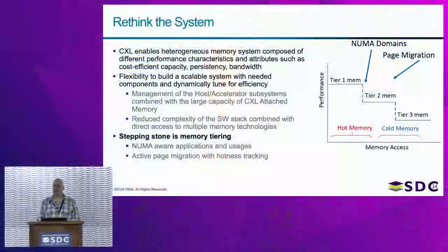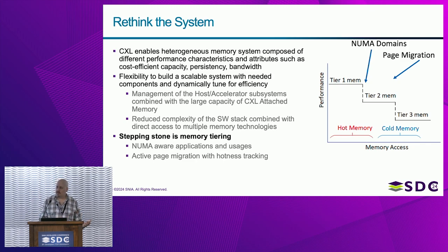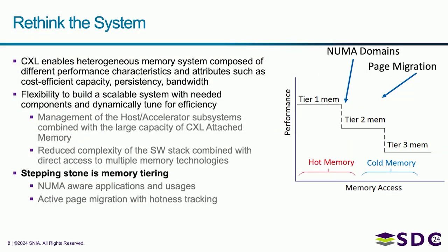Of course, the downsides to this type of architecture are that the farther away you get from the processor, the more latency you have. So these tiered memories have higher latency, which can result in slower performance. Different applications have different reactions to this type of performance. If you saw the talk earlier this morning, you could see some applications don't have much reaction to it. Some other applications slow down a lot. You also need the software infrastructure to manage this memory. Traditional operating systems understand the difference between traditional storage, SSDs, hard drives, and main memory, but don't necessarily understand the memory tiering idea. So there also needs to be a software infrastructure to make this work correctly.